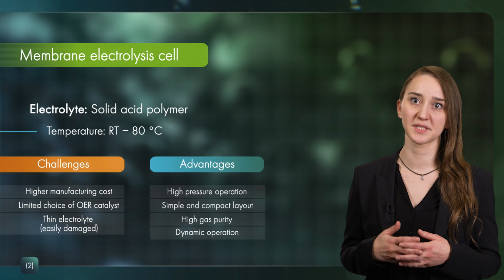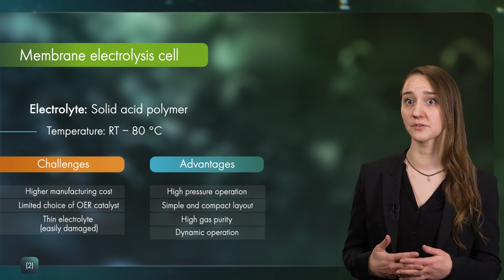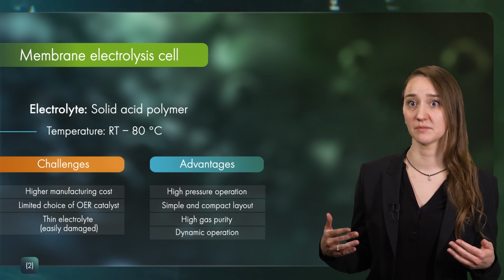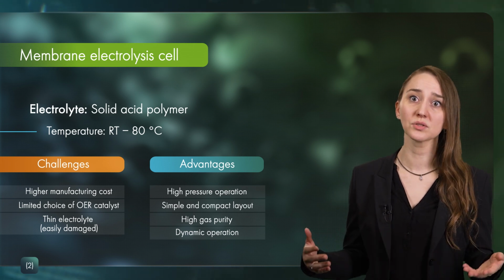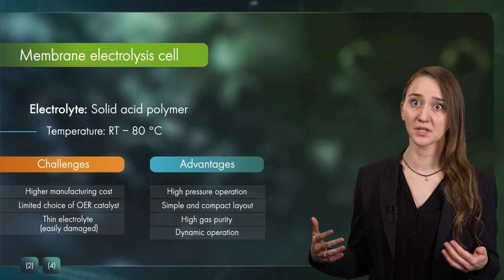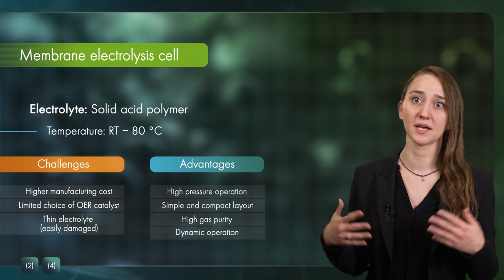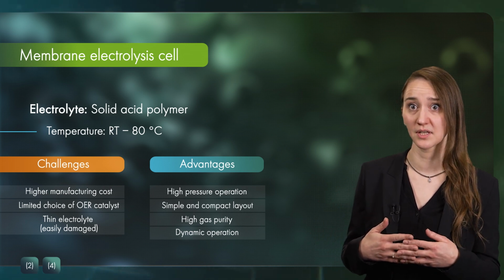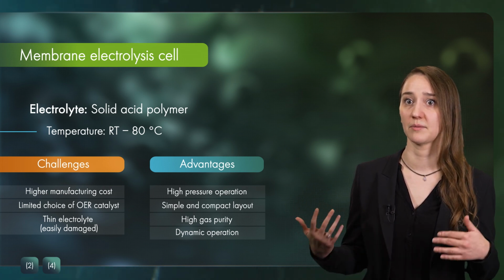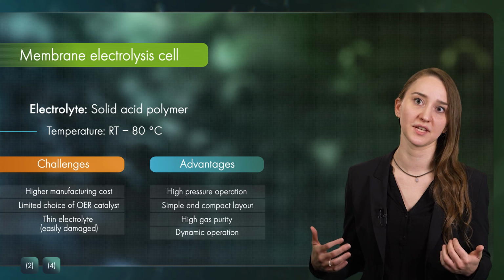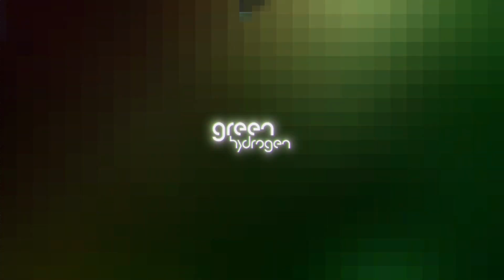However, the materials that withstand the environment of this type of electrolysis cell are very limited and those that are suitable are typically pricey. They also contain perfluorinated polymers, which have come under scrutiny as so-called forever chemicals, and are being banned to an increasing extent. So cost, environmental aspects, and material scarcity are issues.